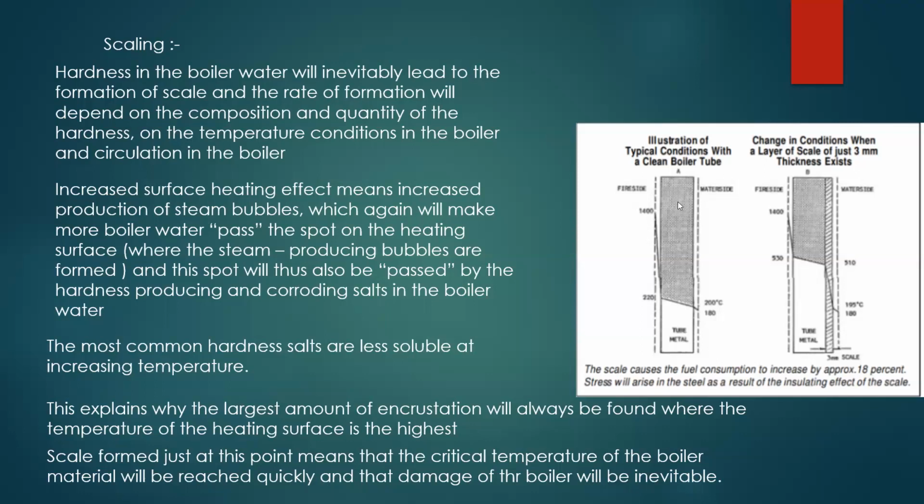So now you see, this is the water side, this is the fire side. Your boiler is clean. Can you see small deposits here? Can you see one extra line in this one when you compare both figures? Yes, sir. So these are the scale, and when scale forms, can you see the temperature is reducing? We are following a different graph.